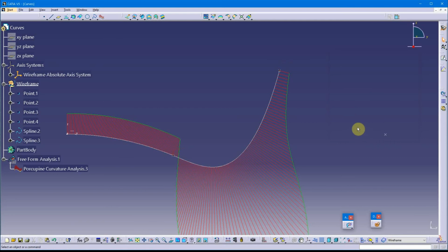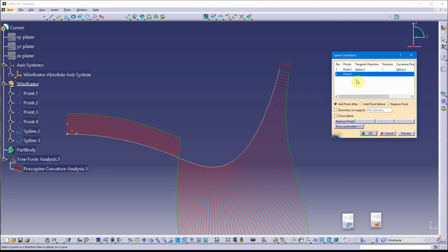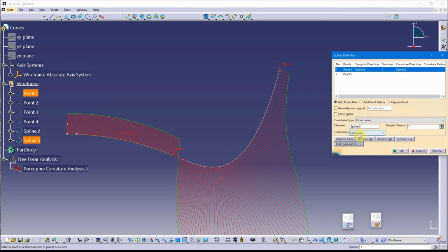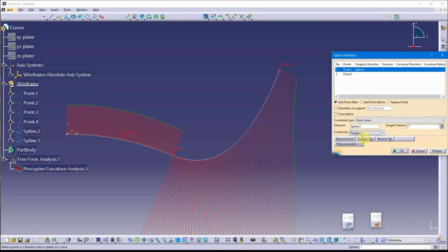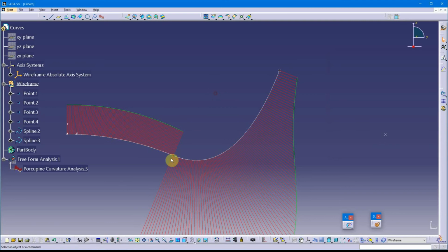When I remove that tangency, I want to back this up a step and clarify this because it is very important. I'm going to back this up to tangency continuity. Right now this curve is second degree, because it's between two lines and I have tangency or continuity added here. So first degree, then adding the tangency continuity makes it second degree.